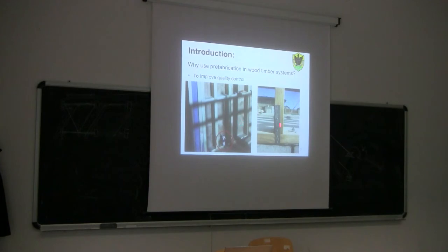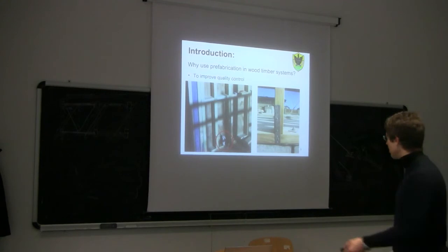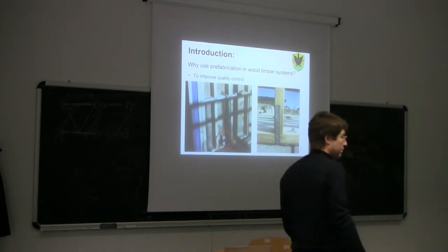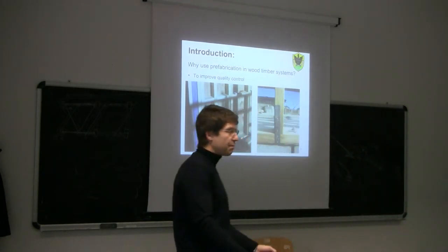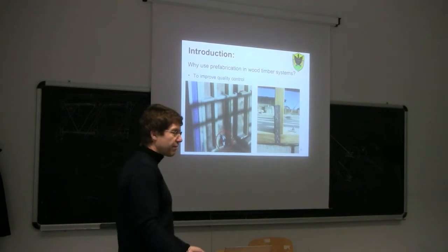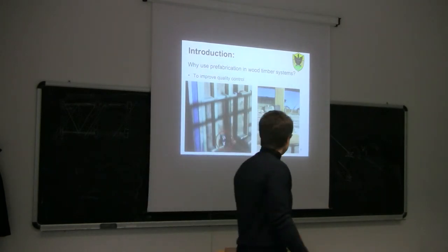Or, as you can see here, theoretically, this connection should be straight on the centroid of the two members. Instead, as you can see, it's not really on the center. So those are typical mistakes that we can find on the building site.